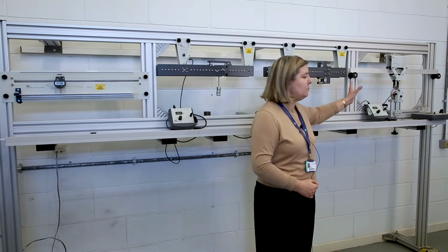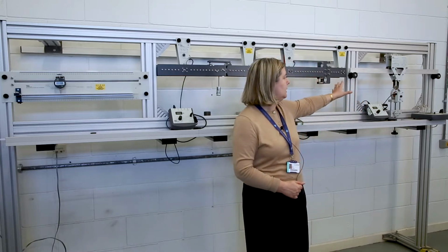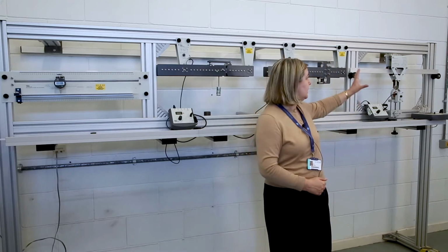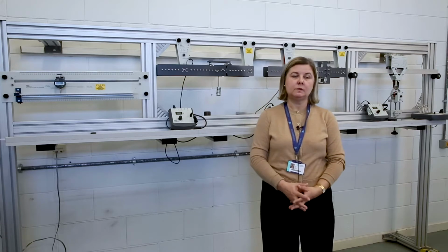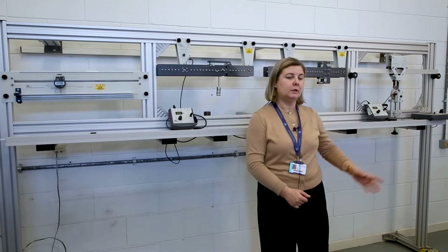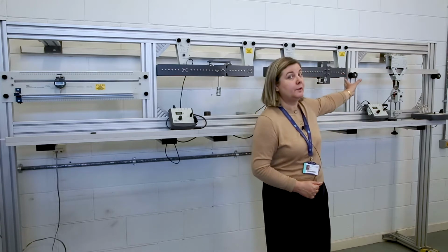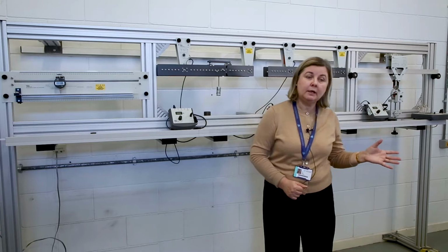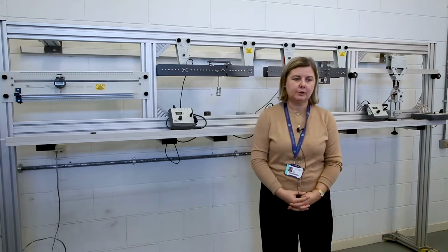Similarly, for the bending stresses in the T-shaped beam, students will need to carry out experiments and do theoretical calculations, which would also include the calculation of the position of the centroid for the T-shaped beam, the calculation of the second moment of area of that section, and the position of the neutral axis for that particular section.